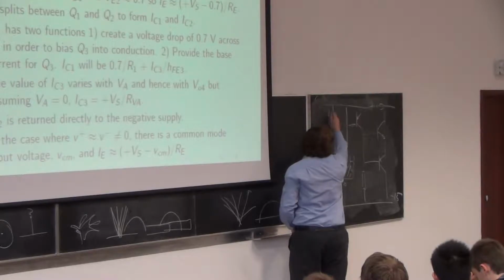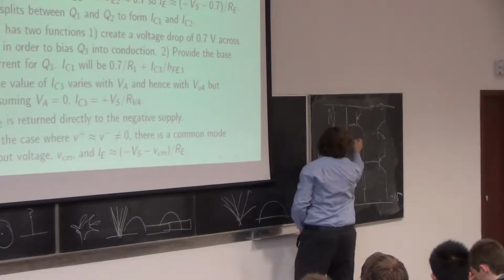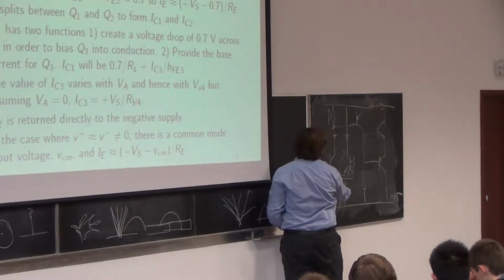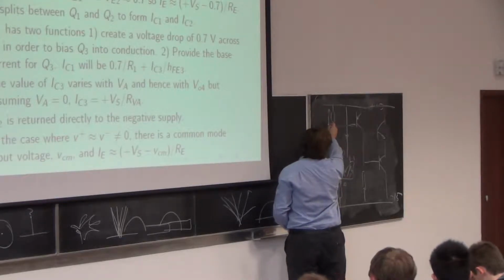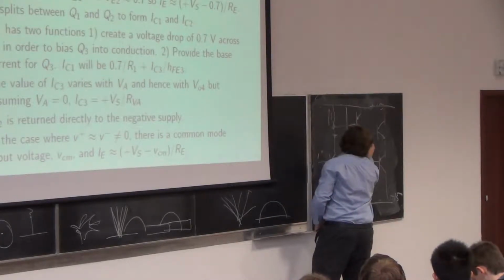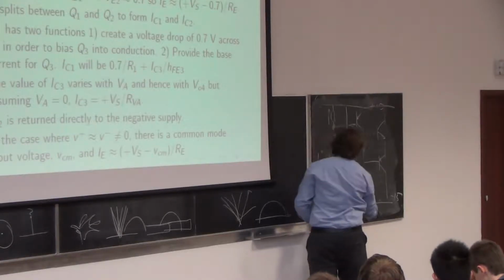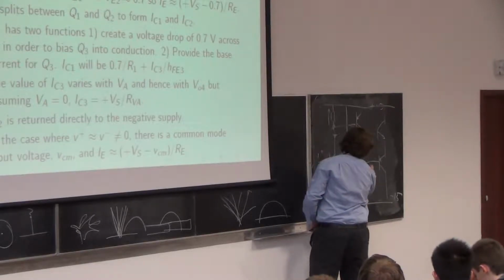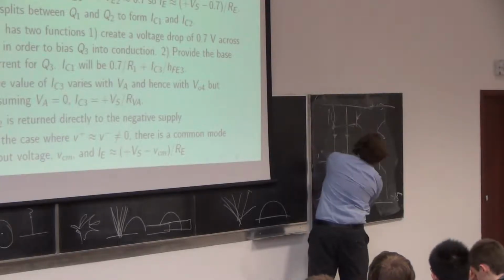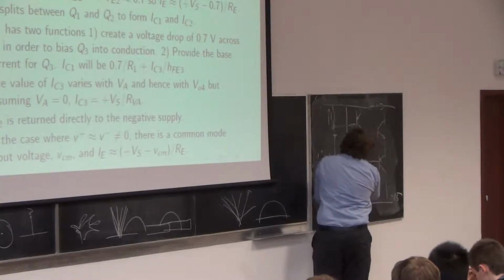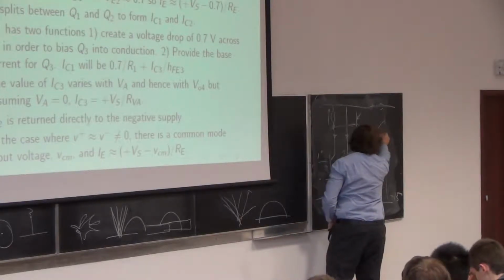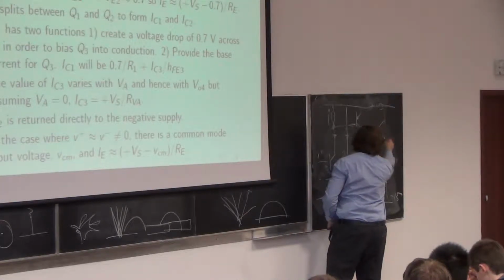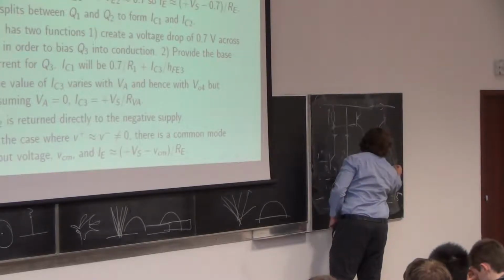So this current in here will increase slightly, current in here will increase slightly, half as much as the increase there. The voltage drop across here increases slightly. This transistor turns on a bit more. This current increases a bit. Voltage across there drops a bit. These two move down in voltage because this voltage is getting bigger. Sorry, up. These two must move up in voltage because there's something here which is taking up more voltage. These two moving up in voltage. This one turns on more. This one turns off more. Current flows through there. No, I didn't draw a load. The current down there like that.